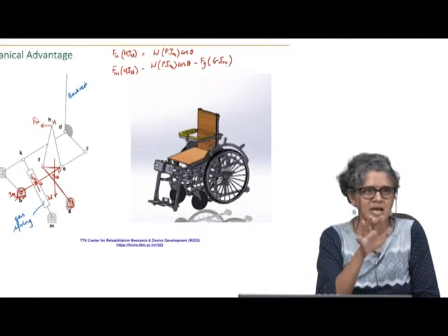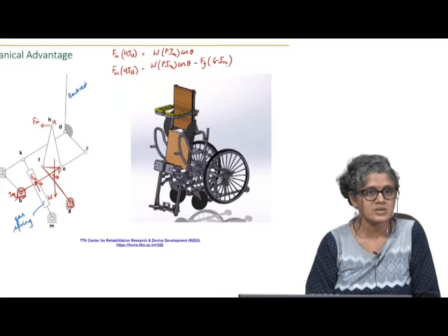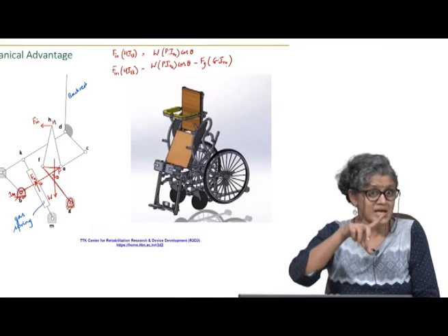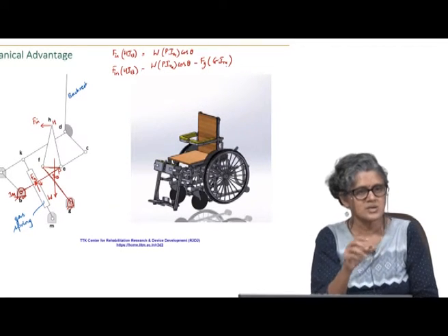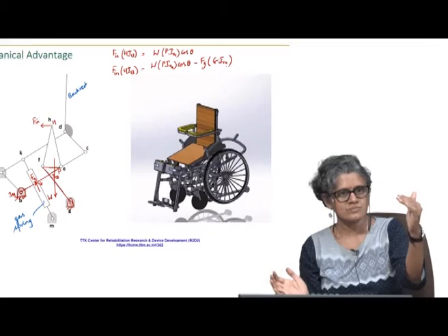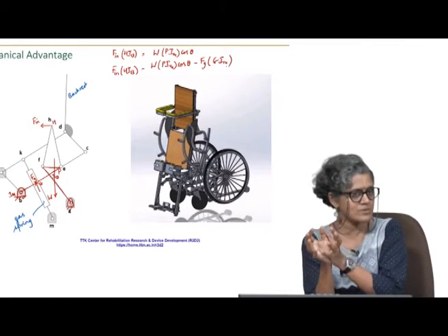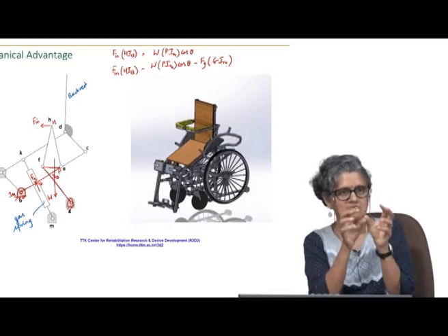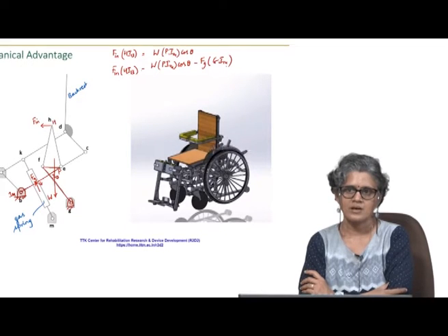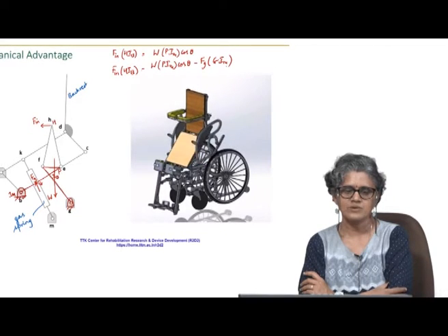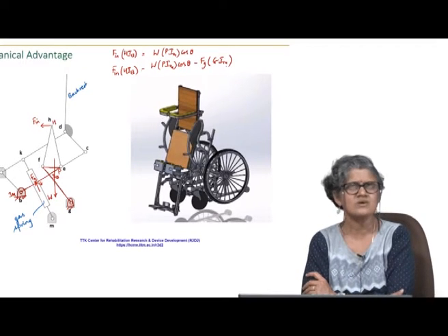This is sort of the idea behind spring balancing also. Force is constant, so that will also vary as the length changes. There will be a constant force plus a force due to a regular spring, right. In a regular spring you have F equal to Kx. Here you will have a constant force plus K times the displacement.